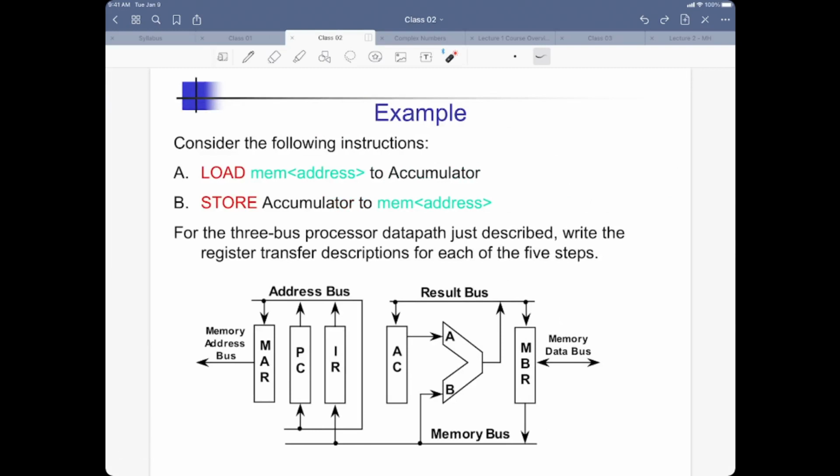Let's do a couple of examples here. Actually, we are doing the load example, and if I remember correctly, store is the example that you guys are working on. So when I say load, I'm moving from memory to register, from memory into the accumulator. The mnemonic for this is LDAA, which stands for load accumulator A. Why the need to say accumulator A?